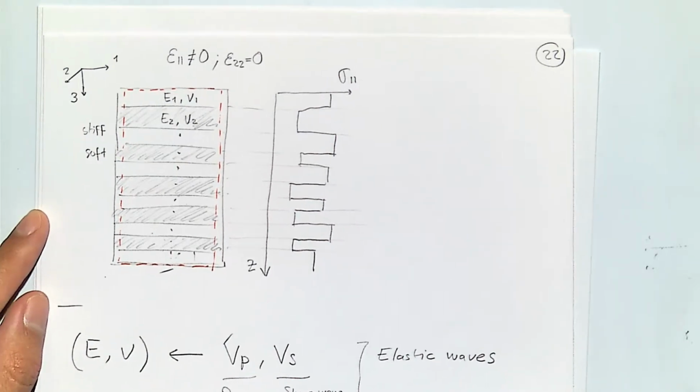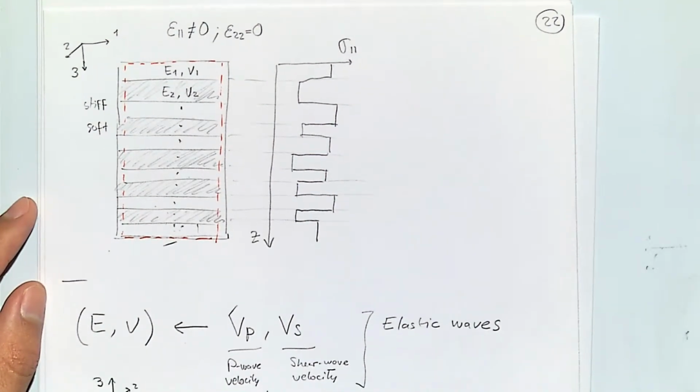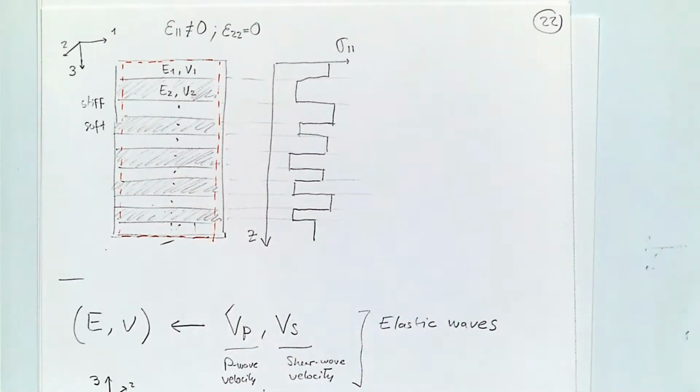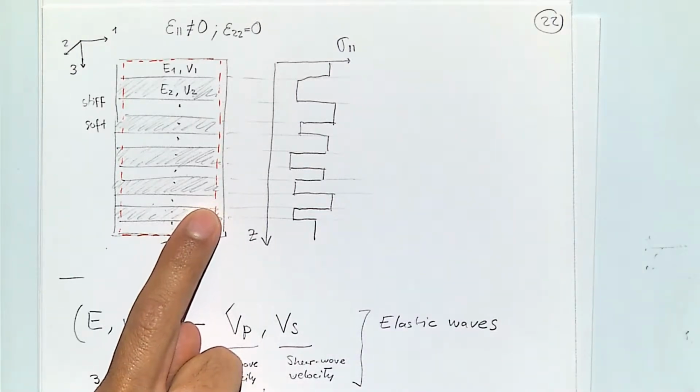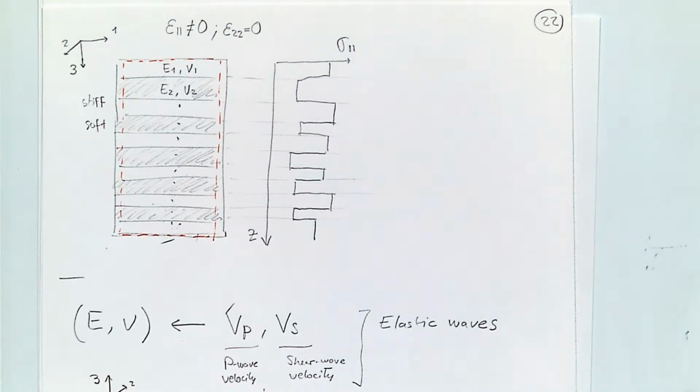Yes, Jack. The previous one, when we assume that epsilon 1,1 is not equal to 0 and epsilon 2,2 is not equal to 0, and we assume sigma 3,3 is the vertical stress. Are we assuming the stress regime is reverse faulting? No, because those strains can be significantly small, so that the horizontal stresses are still lower than the vertical stress.